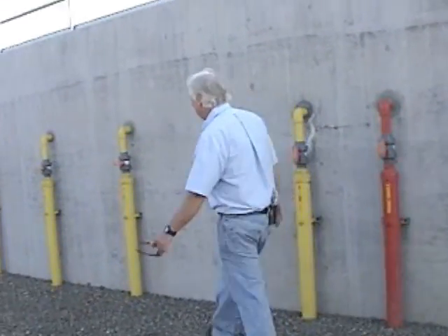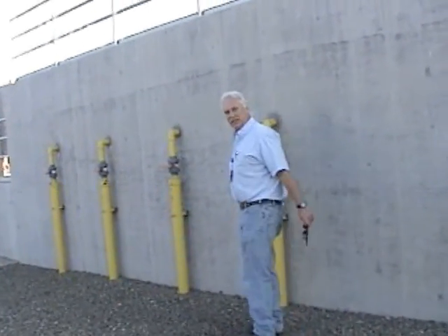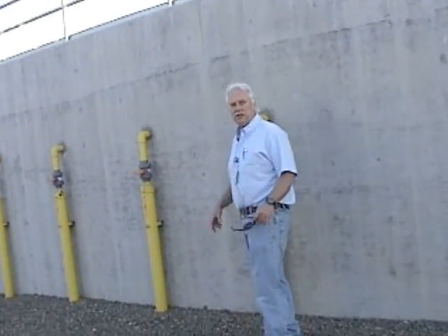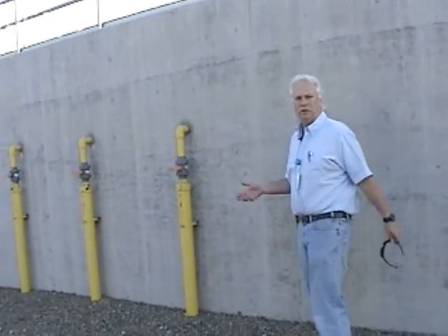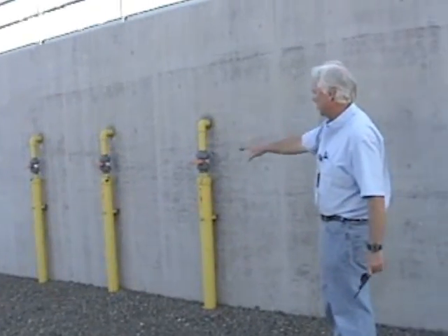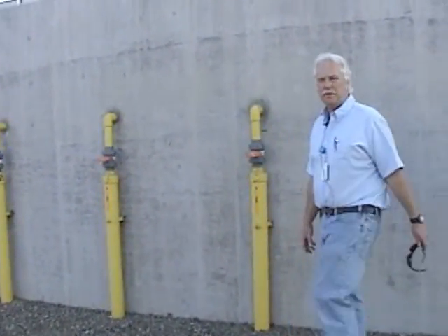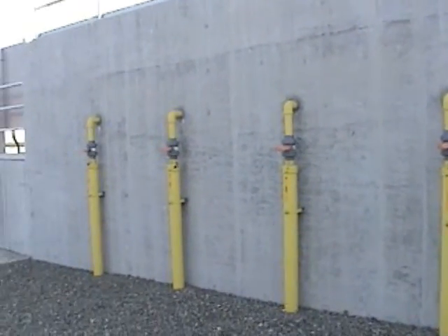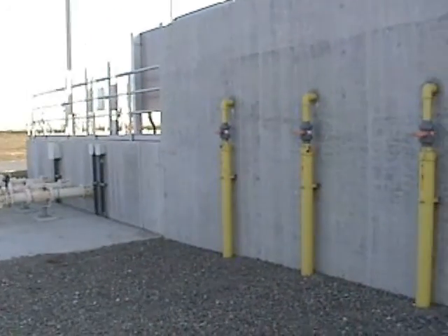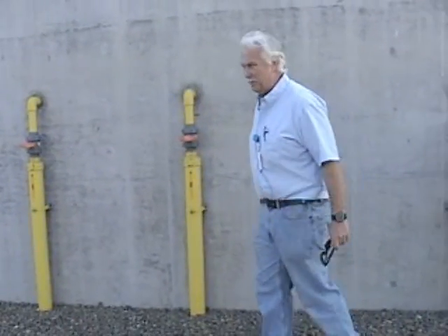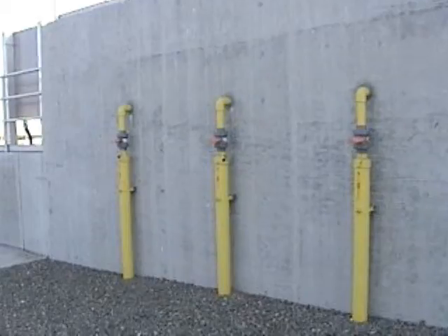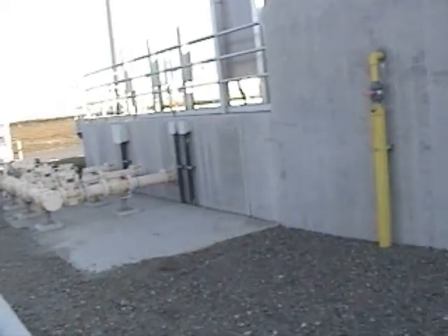And you have several points to bleach the filters, or pre-chlorinate before filtration, and these would be the lines you'd use for that. We've never had to do that here. The turbidity coming off the secondary system is usually less than 1 NTU, and most of the time I see about 0.5 NTU coming out. So we've had real great luck. We haven't had to do anything extreme with chemical addition.